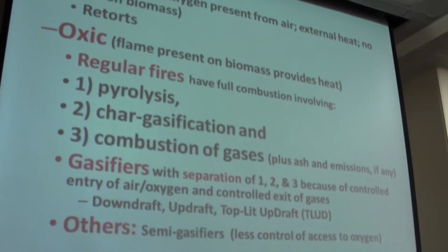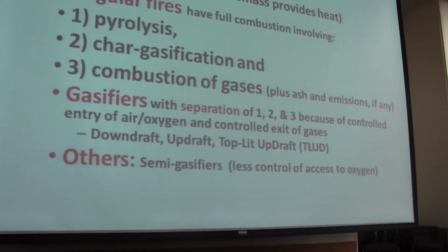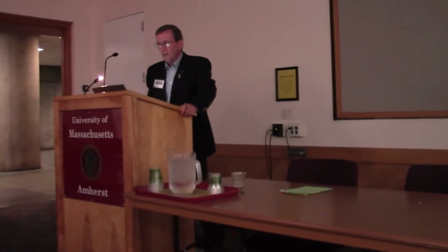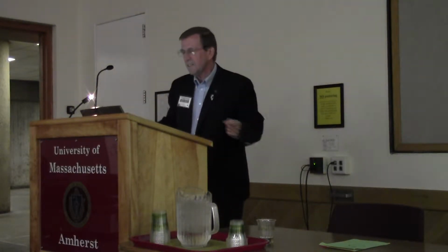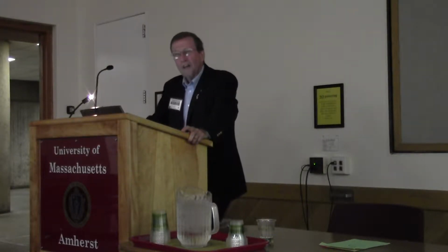There's no flame in the biomass, and this is characterized by the retorts, and they deserve definitely their part of the attention. Oxic, the flame is present. In a regular fire, you have pyrolysis, char gasification, and the combustion of those gases that come off of it. And they're all occurring almost simultaneously in the same space. A gasifier, there's the separation between these 1, 2, and 3, which are listed there, and then there's multiple types of gasifiers, and we can talk about that.